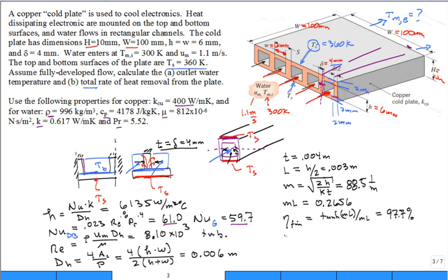What we want to do is compute an overall efficiency for convection off of both the unfinned base part, if I can emphasize it like this, that's kind of an unfinned base part, with the finned part right there. And I'm just showing you half of it there.